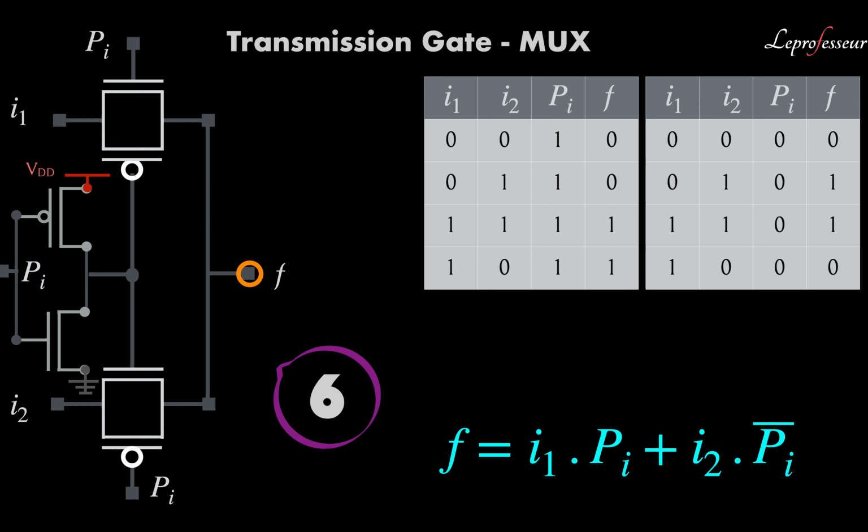You can model it with the RC lumped model if you have more transistors in that transmission gate structure. It becomes like multiple resistors in series for complex logic gates, or in parallel, so you can develop an equivalent RC circuit delay model for that. We'll be discussing that in coming lectures.